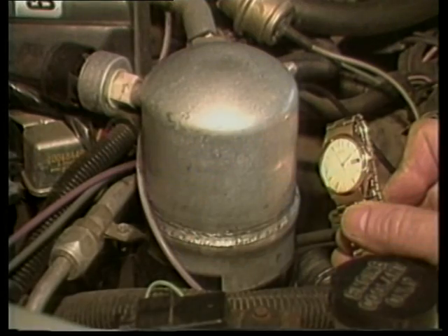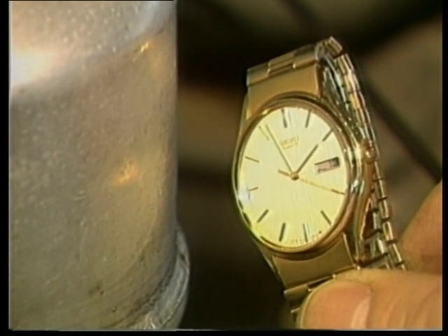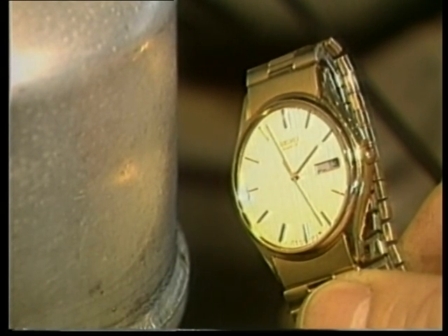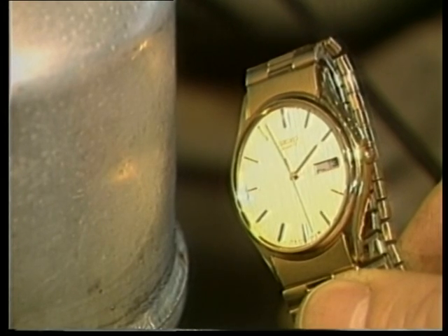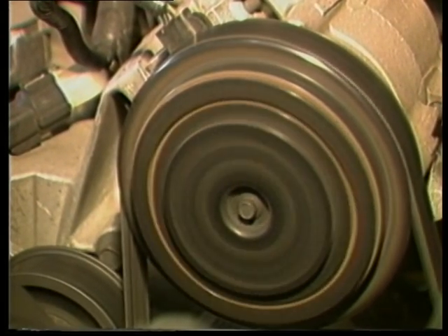An easy trick for finding a plugged or damaged orifice tube during your inspection is to shut the AC system down and listen for the hissing sound of an orifice tube. The hiss should last about 30 to 45 seconds before stopping. If it hisses longer, blockage is indicated.